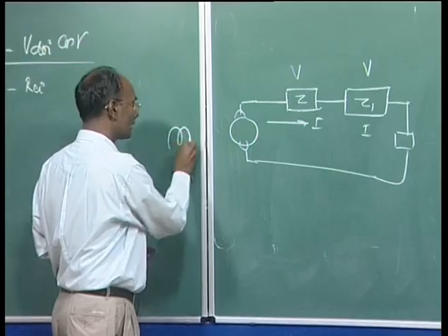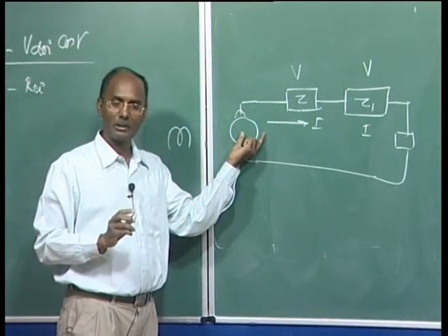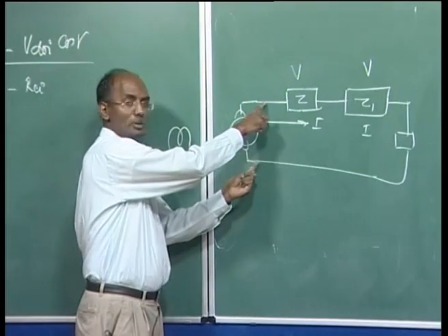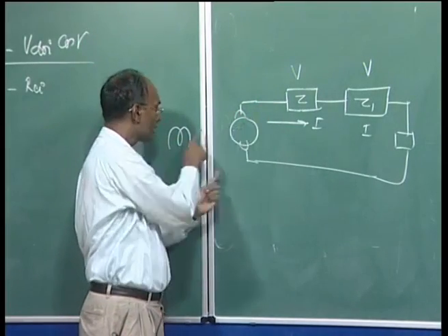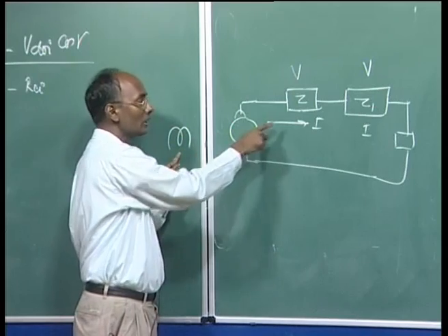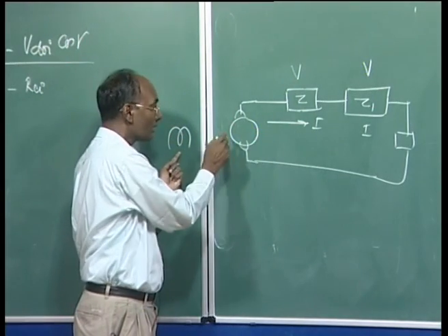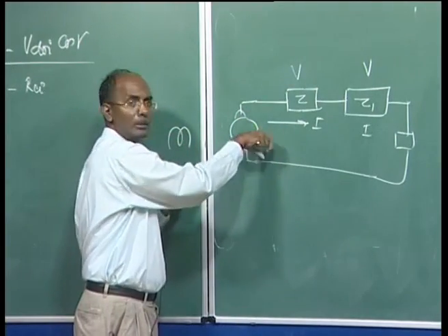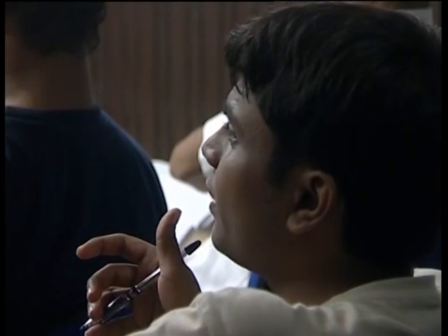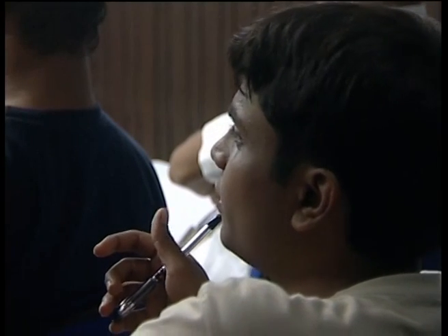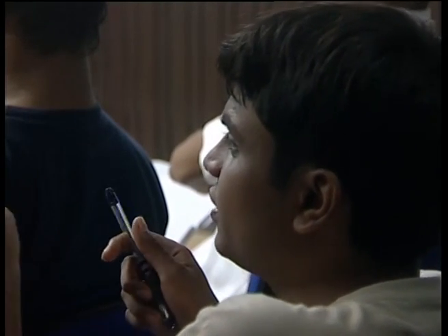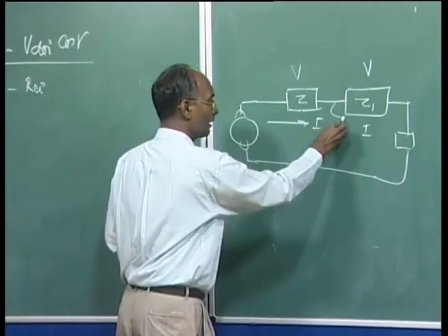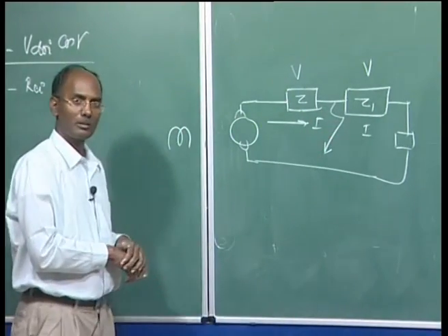Listen, whatever DC generator you have, whether series, shunt or separately excited, you can change the voltage, and you do this by changing the field. You measure the current, compare it with the reference current, and change the field accordingly to maintain the voltage. To maintain constant current, we change the field. So in the case of a fault, the current will suddenly go up.